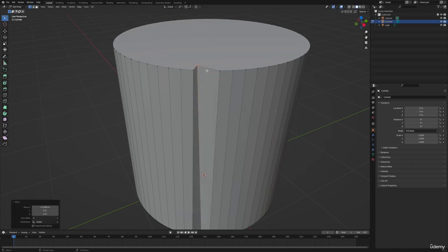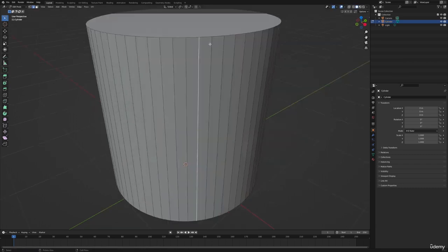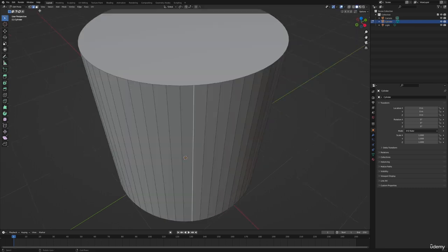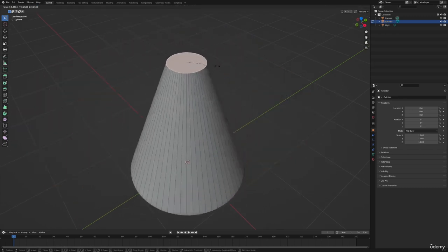We can also move the point on a specific axis if we want. With the same commands that we learned before, we can then select an edge, for example this one, and we can move it with G, as I said, on all three axes, as well as scale and rotate it. We now have an edge made up of 2 points, so we have multiple dimensions. This means that all three transformation types are now possible. The same then also applies to the faces. If we now press 3 on our keyboard, we can select faces. I'm going to choose the top face, for example. And we can now rotate this face as well. We can move it and we can scale it.